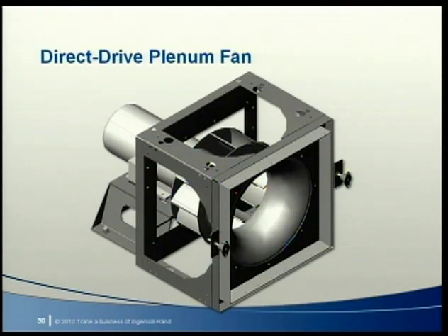With no belts or sheaves and fewer bearings, direct drive fans are more reliable and require less maintenance than belt drive fans. And since there are no belt-related drive losses, direct drive plenum fans are typically more efficient, quieter, and experience less vibration than belt drive plenum fans.